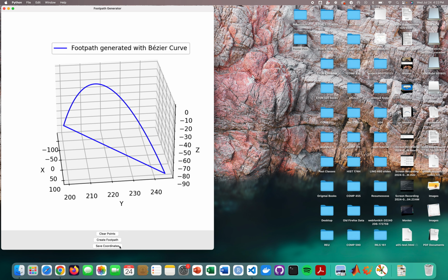Okay, moving on. To check the footpaths to make sure that they were within the robot leg's range of movement, I made this footpath checker, which uses forward kinematics and different combinations of joint angles to create a point cloud to visualize the leg's range of movement.